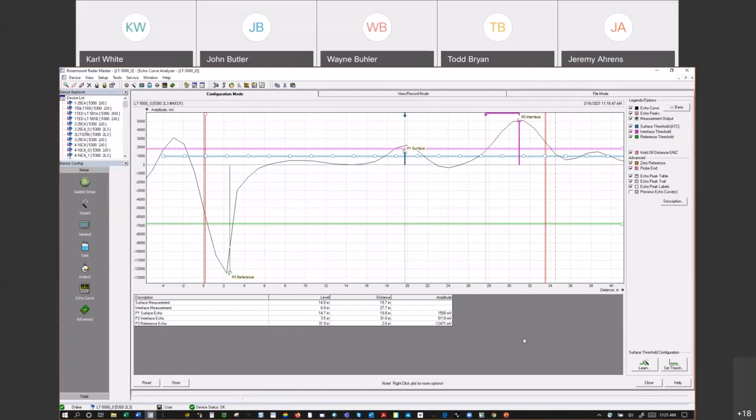So the flippers that you see, the indicator follows that float, right? So if it's calibrated for a 0.8 density, but the density is 0.5 for some reason, it's not going to be accurate. Where your radar doesn't look at density, it only looks at dielectric. So radars are not affected by density changes, but that float is. So just keep that in mind.